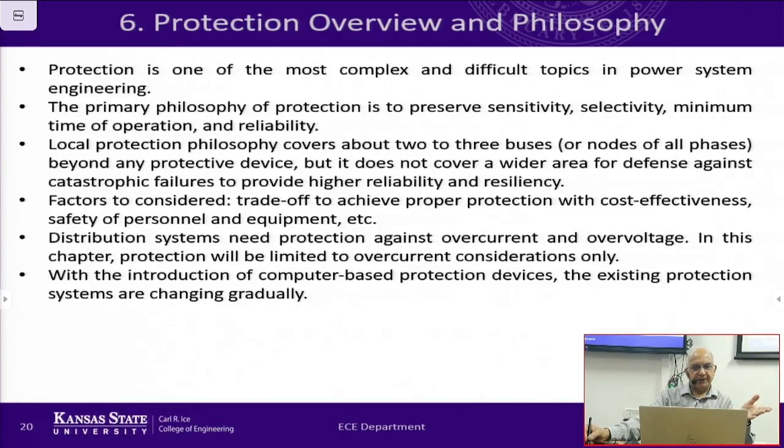And typically, distribution systems will need protection against overcurrent and overvoltage, which will happen when lightning strikes or some switching actions take place, like capacitor switching, which will cause temporary overvoltage. Lightning typically does that, and I think with integration of distributed resources, you could have some additional issues.